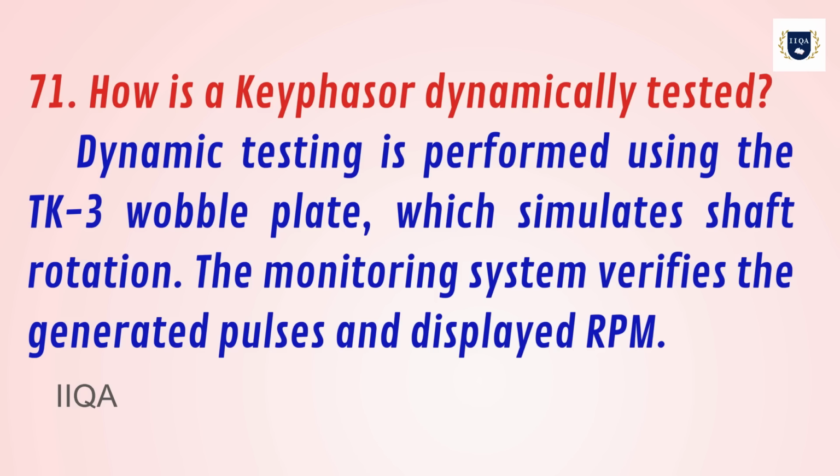71. How is a Keyphasor dynamically tested? Dynamic testing is performed using the TK3 wobble plate, which simulates shaft rotation. The monitoring system verifies the generated pulses and displayed RPM.